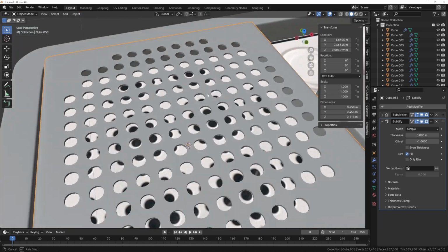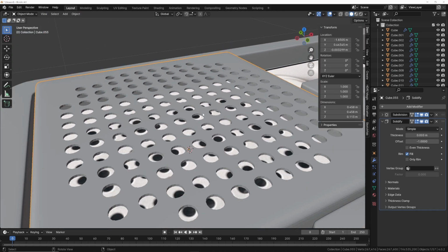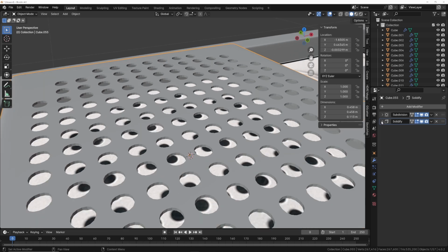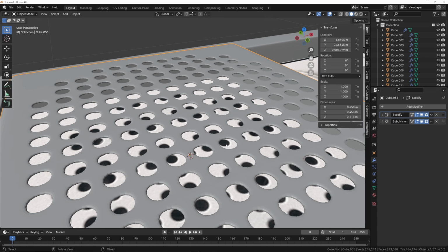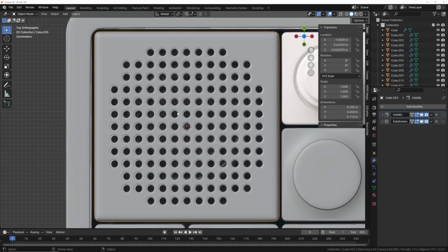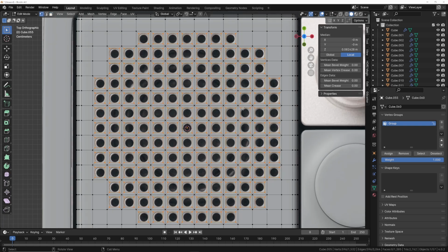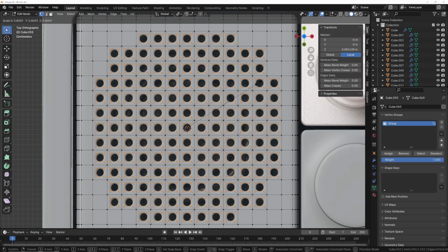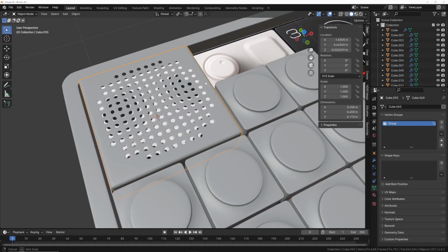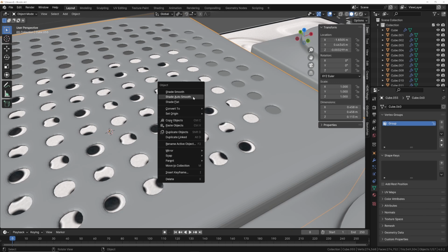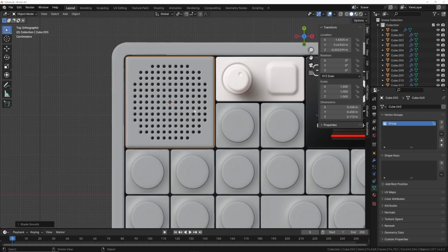Now, if we go to the top, they're perfectly sized, but you can tell that these are sharp edges, and it's going to be hard to bevel those the size that they are. So what we can do is we can tell this to solidify it first and then subdivide it, and what that's going to do is going to round out the edge. But you can see our holes are a little bit big, so if we tab into edit mode and then go back to data, click assign or click select, that's going to let us pick these vertices. So then we can just scale them along their individual origins by changing this point here. We can just scale them down. We can get it to exactly match. And then you can tell there's still some pinching and stuff going on. We can just shade this auto smooth, and that's going to do pretty good for now.